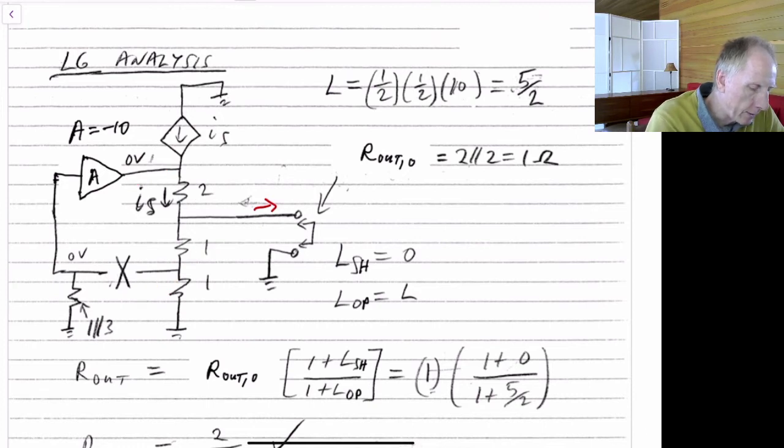So we have the left side is 1 in parallel with 3 ohms. So when we break that, that's the impedance we'll put on the left side, and the right side will be the impedance looking into here, which is infinity. So we could put a resistor here of infinite value, but that's really just leaving it open anyway. So this becomes breaking the loop properly.